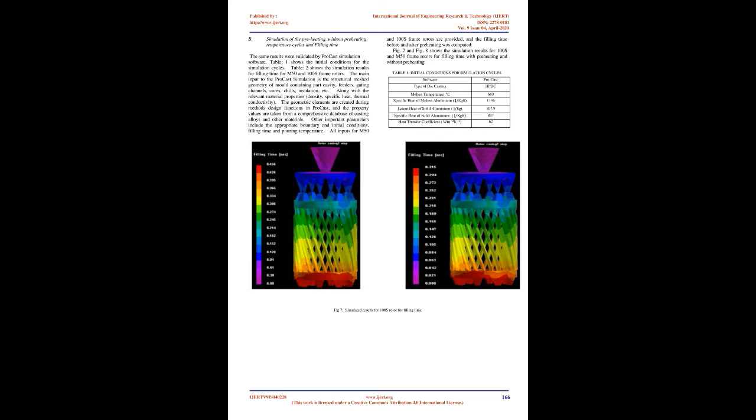The amount of heat leaving the mold with the casting, Q4. Q4 equals W·CPS·(T2 − T0) (5). Where T2 is the temperature of the casting taken out from the mold. The heat balance equation (2) is as follows: Q2 equals Q4 plus Q3.